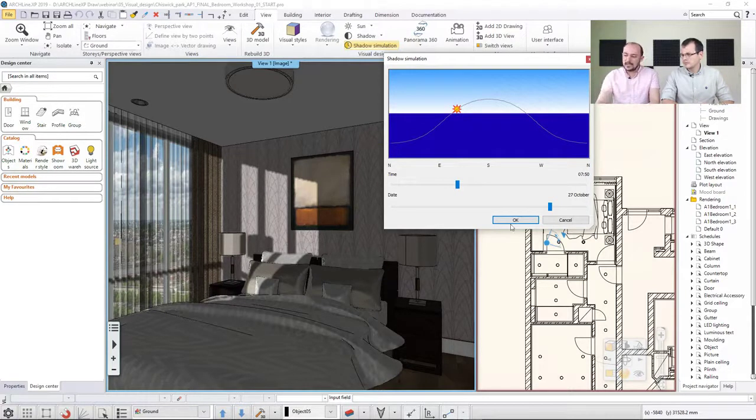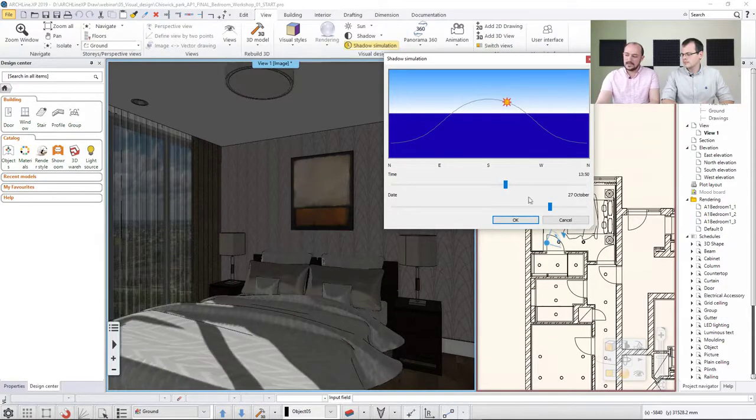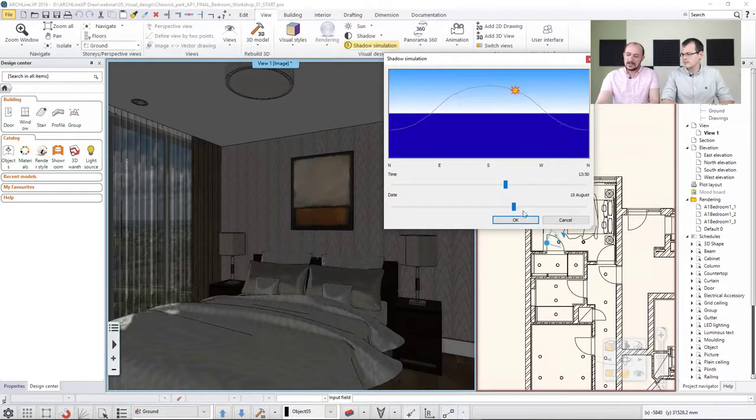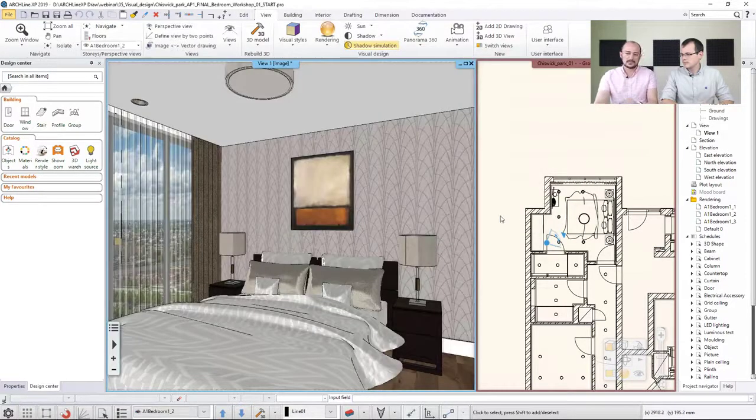But when I hit OK, this will be the sun setting of the whole building. So I can set up something that I like, and then I can simply click on OK, or if I would like to drop it, I just click cancel. So whatever I do, this will affect how the sunlight will behave, how the sunlight will brighten up this scene. It's wise to choose carefully sometimes, when you have a lot of external light coming in, it is easier to burn out the surfaces. I will talk about this when we talk about the material.